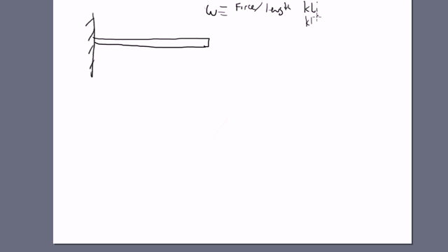I'm going to talk about how one might go about using some mathematics to design. Really curious how Sal Khan gets that line tool to work, so I'm going to try my best here to design something like this. Something that's subject to a uniform load of W kips per foot, defined as force over length. Very often kips per lineal inch, kips per lineal foot, pounds per lineal foot, etc. Span L is going to be typically inches, and deflection is going to be inches.